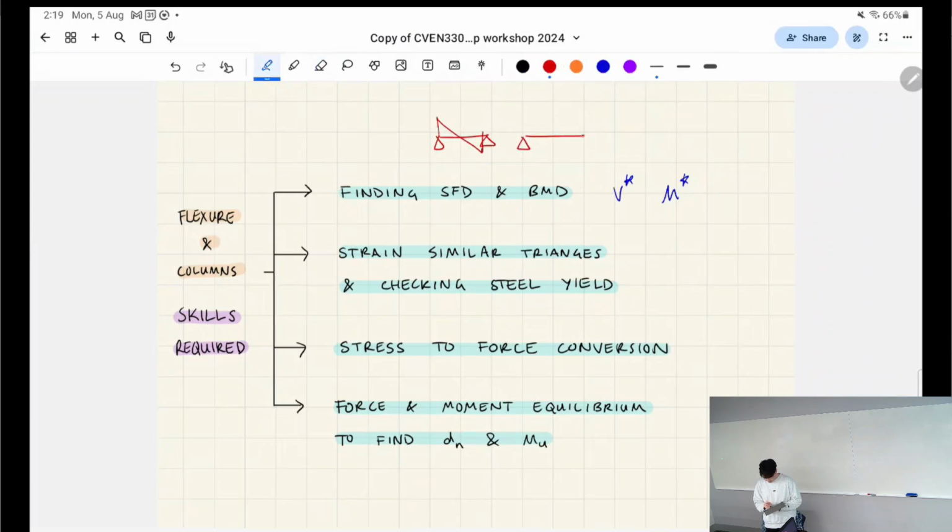And then the bending moment diagram might look like this. If you're wondering where these little jumps are, rather than having a perfect parabola, it's due to an assumption we make with the beam and column connections. It's called a rigidly connected joint.